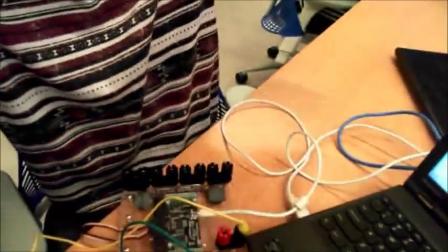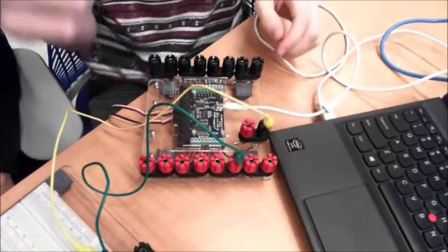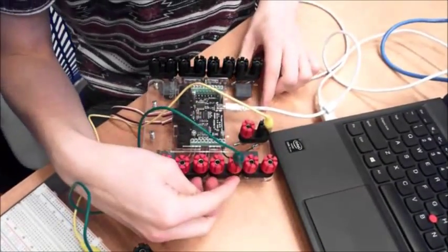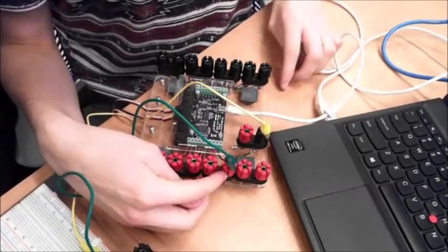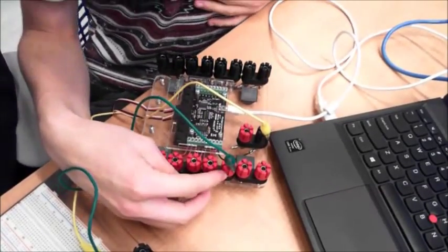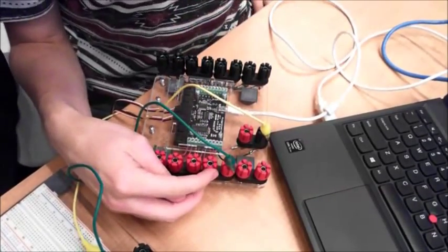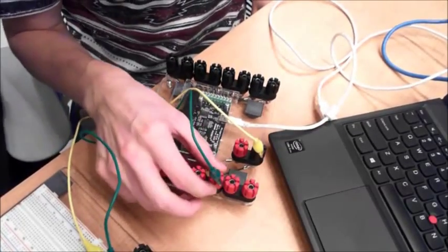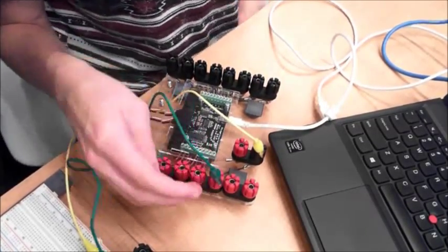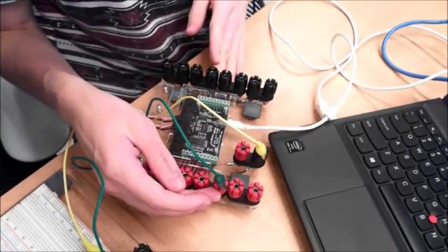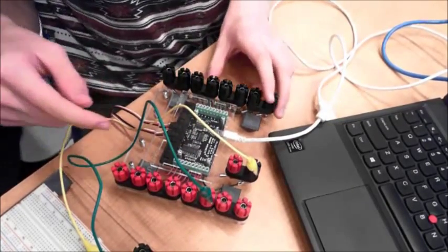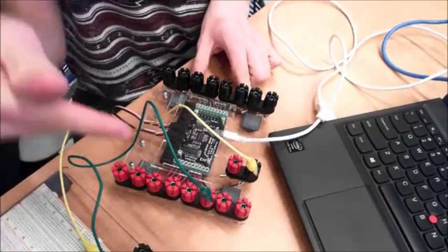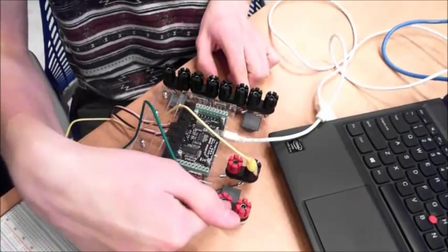So interface on the interfacing board, and it sends the 5-volt signal along output number 2. We are using output number 2 instead of output number 3 because there was a problem with our output number 3 and we were instructed by our TAs to use output number 2 instead. So the reason this is output number 2 is because the output count begins from 0, so it goes from 0 to 7, therefore 0, 1, 2.